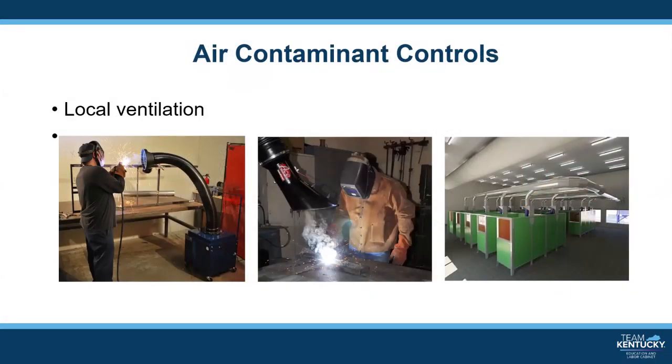Part of the ventilation process, the extraction process, is shown in these pictures of local ventilation. The welding fume exhaust hoods should be placed close enough to the welding arc to be effective, yet not so close as to disturb the shielding gases used or to obstruct the welder's line of vision. The optimal distance from the welding arc to the exhaust hood can be determined by placing the edge of the extractor hood approximately one diameter of the hood from the arc source.